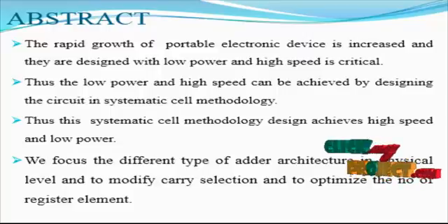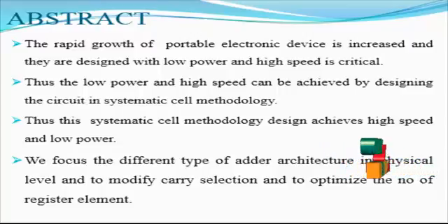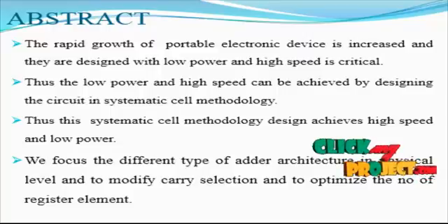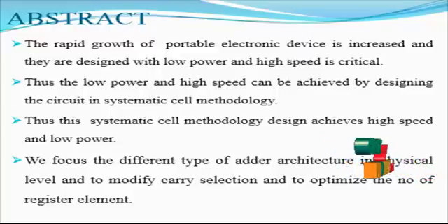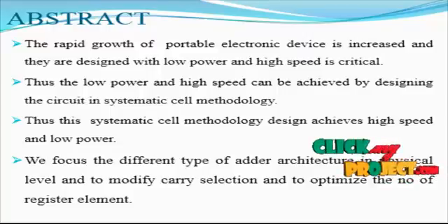The SCDM divides a circuit structure into the main structure and the optimization correction mechanism. The main structure has features including the least number of transistors in the critical path and fairly balanced outputs, being power and ground free and symmetric. The mechanism has the duty of completing the functionality of the circuit, avoiding any degradation on the output voltage and increasing the driving capability.